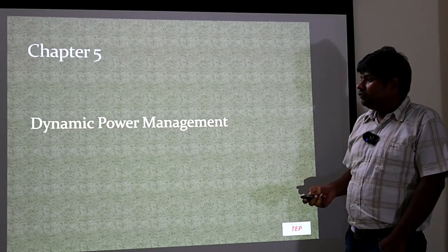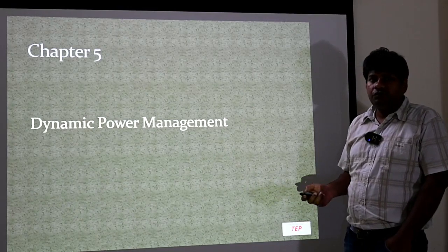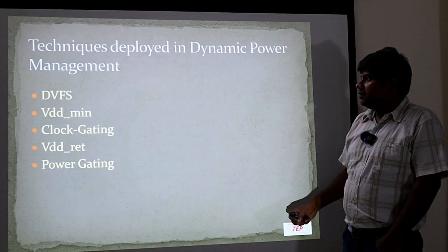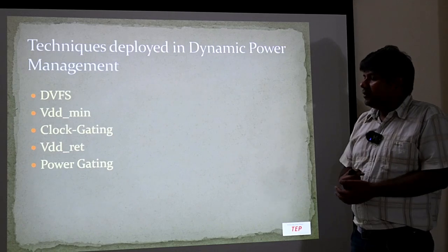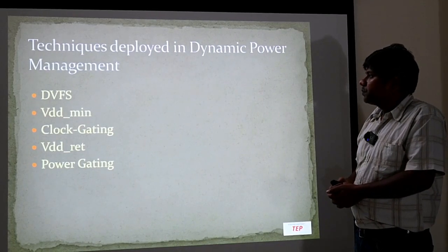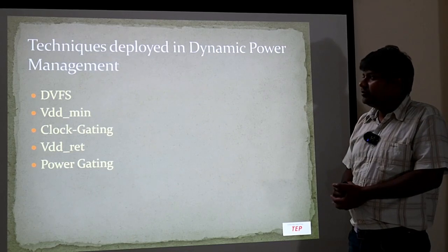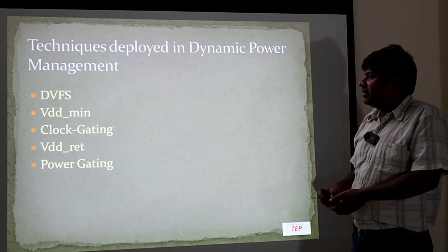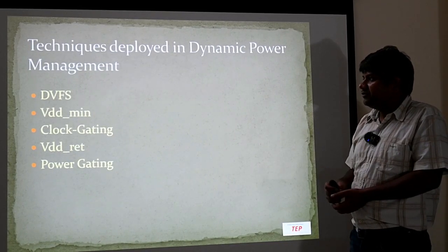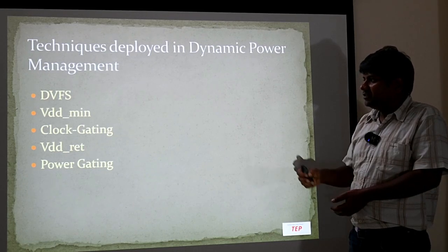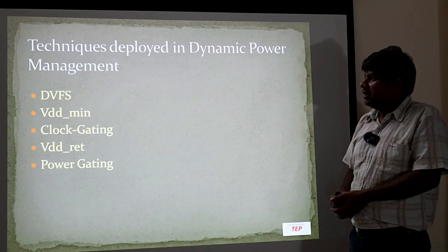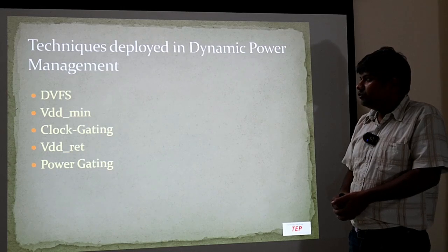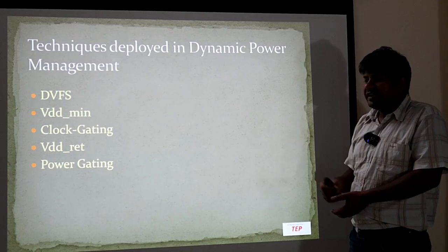Now we'll talk about how we manage power, or basically make good use of those technologies that are in place. Okay, so the techniques that are deployed in dynamic power management will be done using a power management controller in the SOC, a dedicated controller for this. The technique that we deploy is DVFS, dynamic voltage and frequency scaling, and there will be VDD min, where circuits are inactive, then the voltage is slightly reduced. That saves mainly the dynamic power and